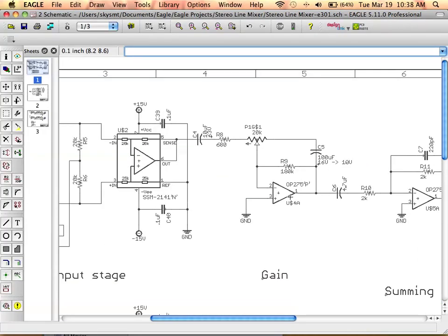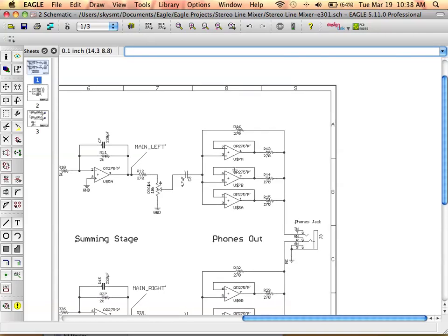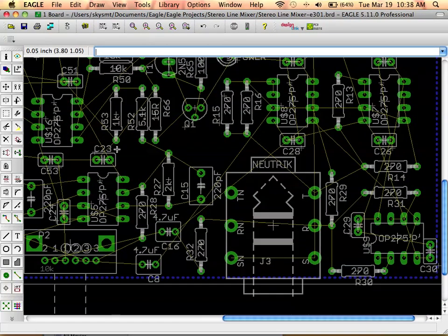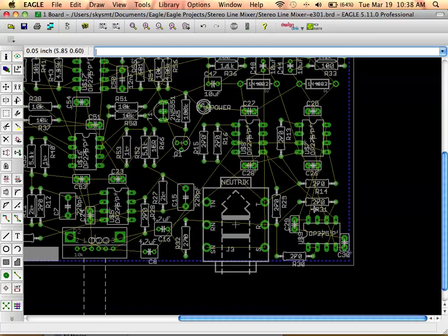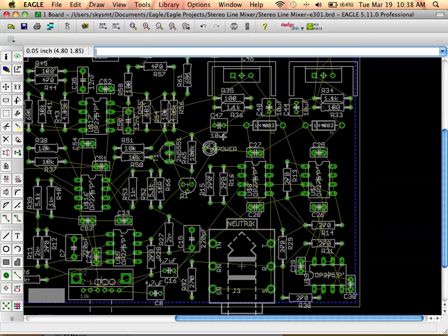You'll notice that I've got capacitors around all the op amps, even the op amps that don't show any caps around them, like U8A. This doesn't have any caps around it, but when I look in the board, U8A, that's what's driving the headphone amp, and where is it? Here's a good technique for you to learn: if you type the word show and U8,